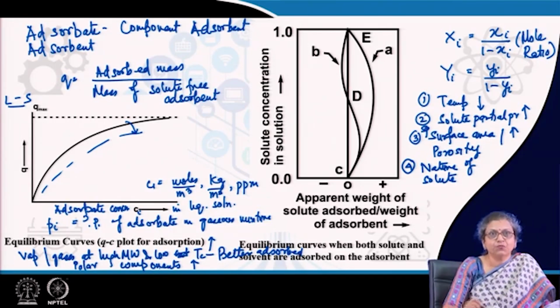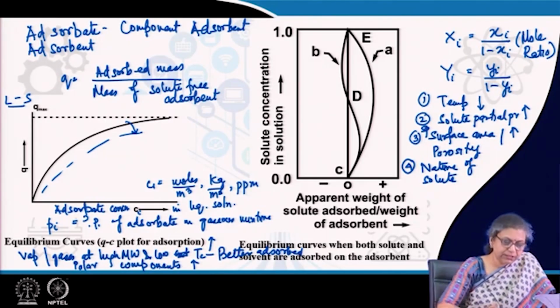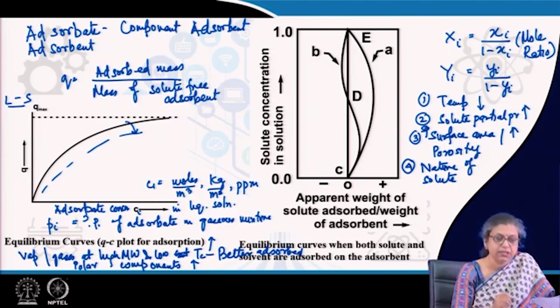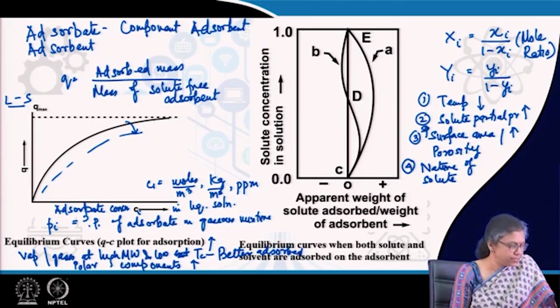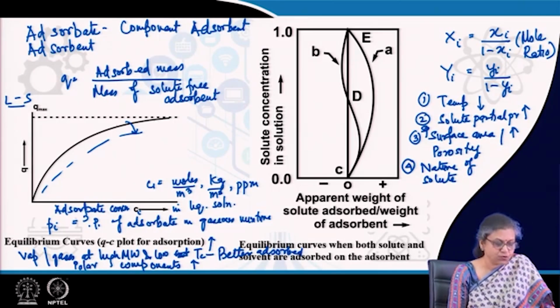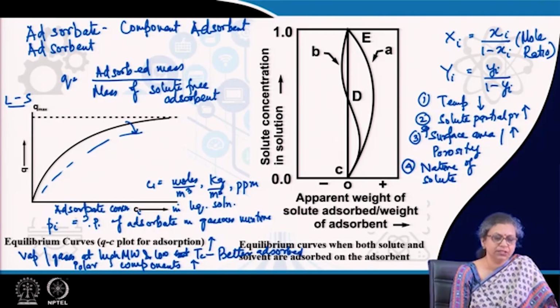Right. Now, there is one other thing that I would like to mention. I have already mentioned that more or less the Q versus concentration curve, where it is usually concentration in the liquid phase and the partial pressure in the gas phase, has the same characteristics. The only thing is that for the liquid solid case, it is not influenced by the solute partial pressure. Otherwise, it is more or less the same, but there is something very interesting when we talk about liquid solid adsorption. If we start with the fresh